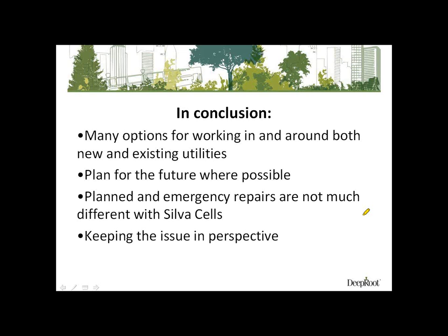Can you talk a little bit more about how compacted the soil inside the system is? Yeah, when we're talking to contractors as far as installation, we talk about foot pressure, roughly 80% density. So Silva Cell is 16 inches tall. Each frame is 16 inches tall, and we have the contractors fill each frame in 2 lifts. So they'll put about an 8-inch lift in the first frame, walk through that, spread that out, just make sure they get their feet on it. They don't have to stomp or do anything special. Then put another lift in and walk over that, and then they would start on the next lift.